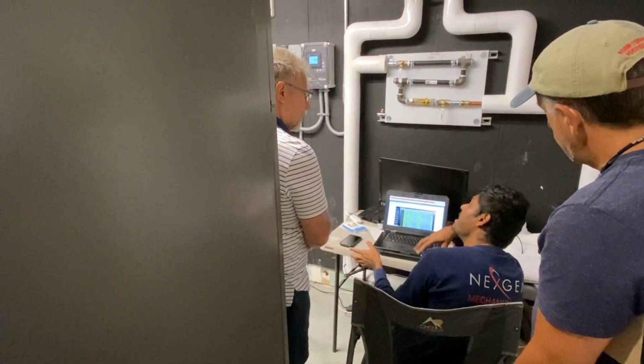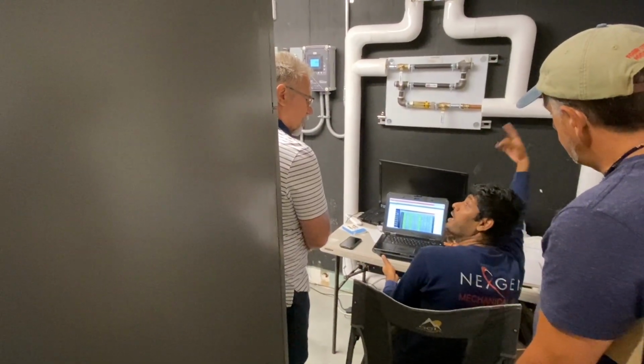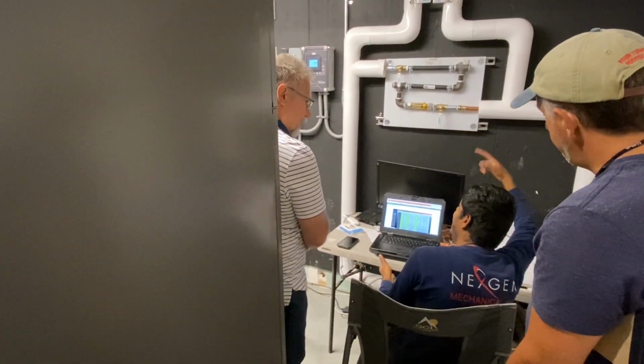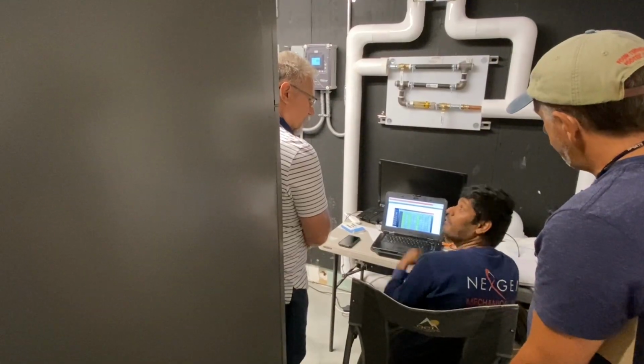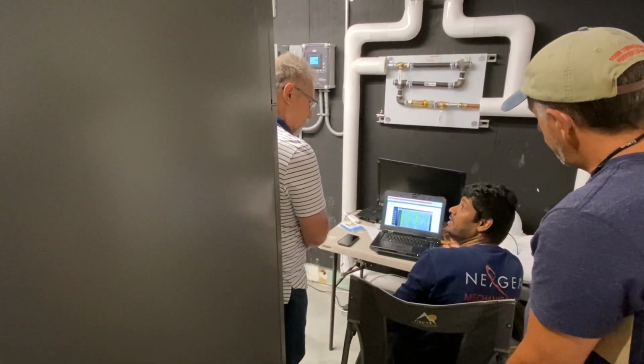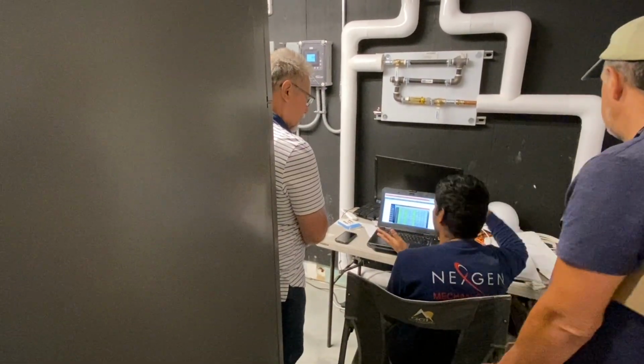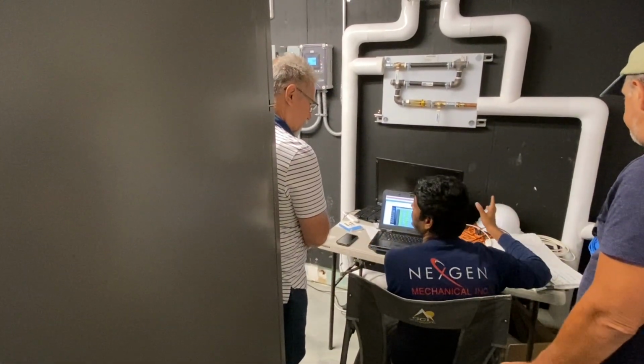Now it tells my RTU, you should be in warm up, or you should be in cool down. And then the RTU tells my VAVs, we are on warm up, we are on cool down, now open all your dampers to max. So that is how the chain of communication or sequence works between the VAVs and the RTUs.